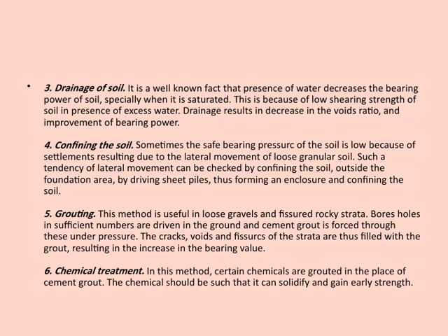Then there's grouting, which is especially useful for loose gravels and fissured rocky layers. The process involves drilling boreholes at strategic locations and then forcing cement grout through these holes under pressure. This fills cracks, voids, and fissures, effectively increasing the soil's bearing value by consolidating the strata.